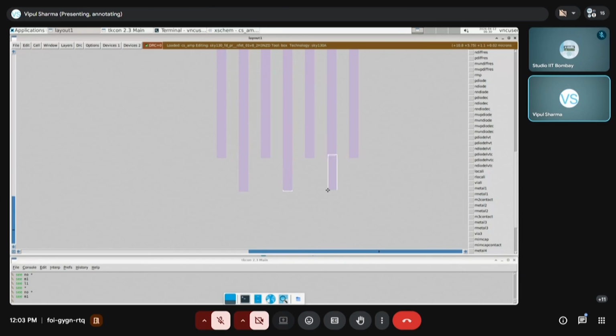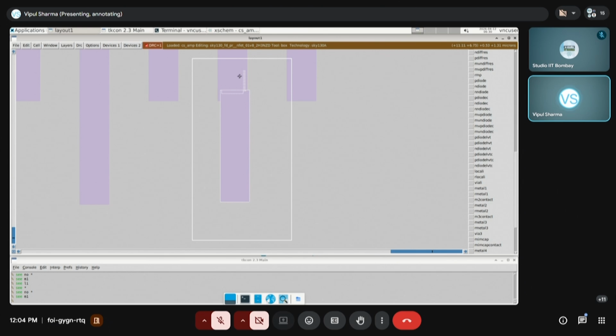Similarly here, maybe later we can see, but this is how a DRC error comes up. As I mentioned earlier, Magic has a very good feature: it can detect a DRC error on the go. So as soon as I put this layer here, it is showing me there is some DRC error. It will highlight that there is a DRC error due to this metal 1 layer being misaligned with this finger source terminal. So that's why this error is coming.